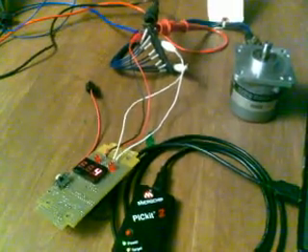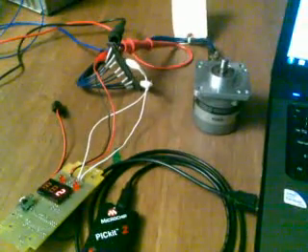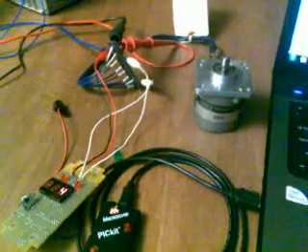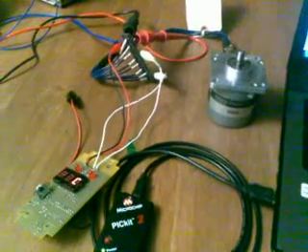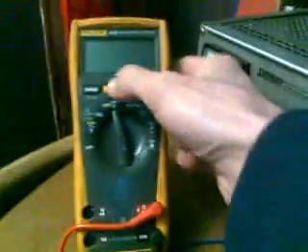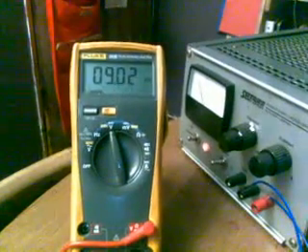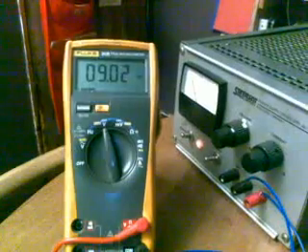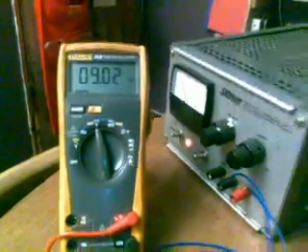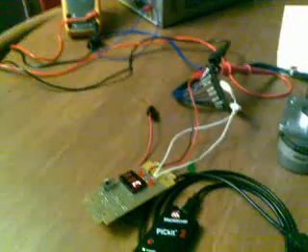The microprocessor really wants to see a strong 5-volt pulse, which means the encoder needs to be well above 5-volt input. So 9 volts would be great, except the battery, when you plug it in, just drains down really fast. So I have the whole thing powered right now by a power supply running at a solid 9 volts. It draws about 150 milliamps.